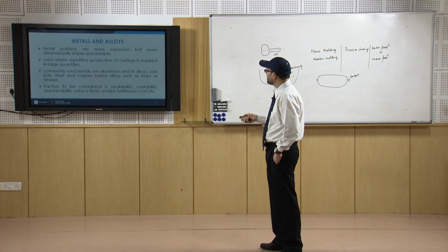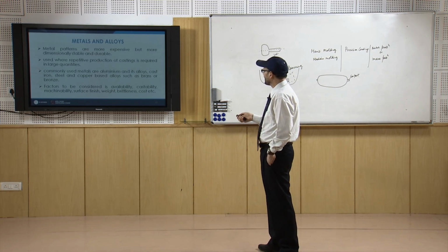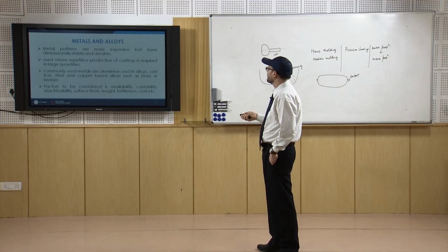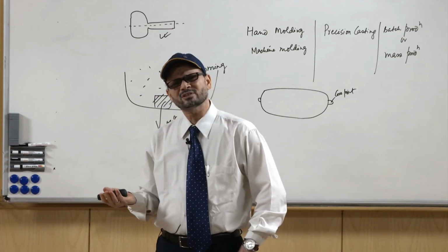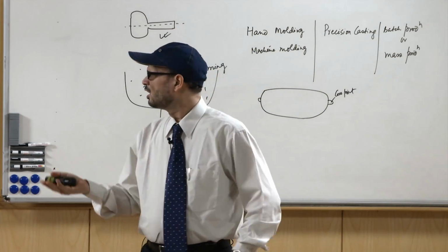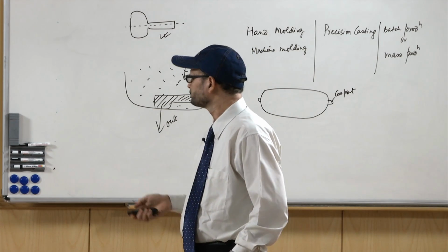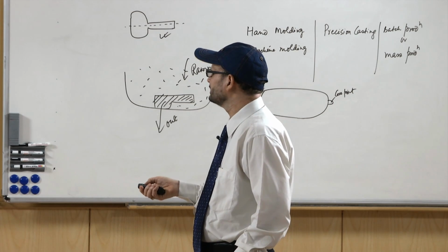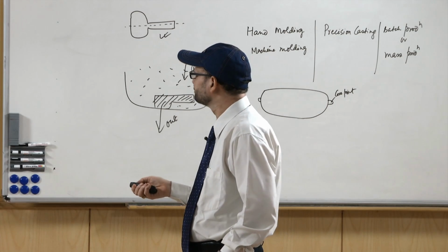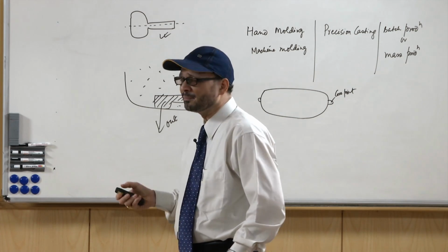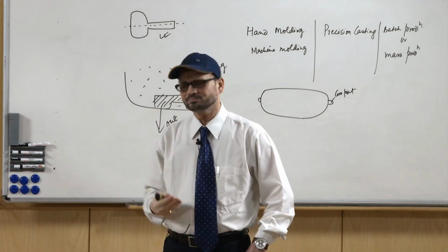If you look at machinability, cast iron has good machinability. Copper or its alloys also have good machinability. Surface finish: with most of the metals we will have a better surface finish, especially with aluminum, or even with steel the surface finish will be quite good, or copper even. Weight: in that sense aluminum is the preferred choice, because aluminum is light. Brittleness is a problem, and cast iron may fail in this aspect because cast iron is brittle.